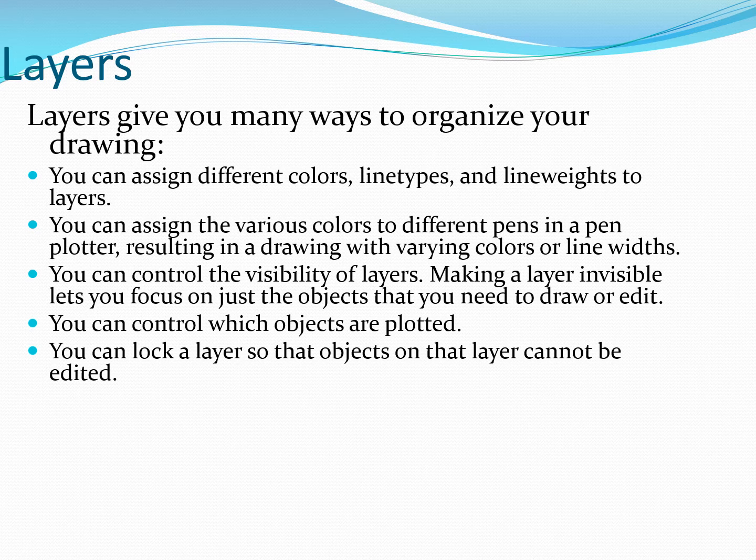Layers give you many ways to organize your drawing. You can assign different colors, line types, and line weights to the layer, and you can assign the various colors to different pens in the pen plotter, resulting in a drawing with varying color and line width. You can control the visibility of the layer. Making a layer invisible lets you focus on just the objects that you need to draw or edit. You can control which objects are plotted. You can lock the layer so that the objects on the layer cannot be edited.